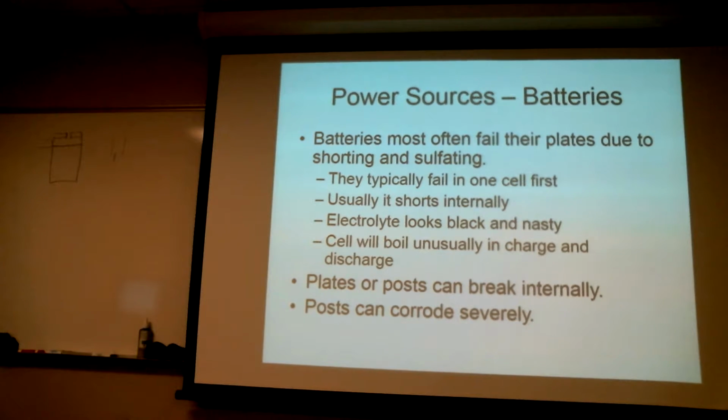So one of the things I do, if it's the type of battery where I can pull the caps off, is put the load tester on there, get ready to go, boom, and then look. If I see it starting to go, then I start looking for the cell. Sure enough, one of them will start bubbling, like the witch's cauldron, right? At that point, you have compellingly identified it: not only does the battery load test show a discharged or shorted cell, but I can actually see the cell behaving in a shorted manner.